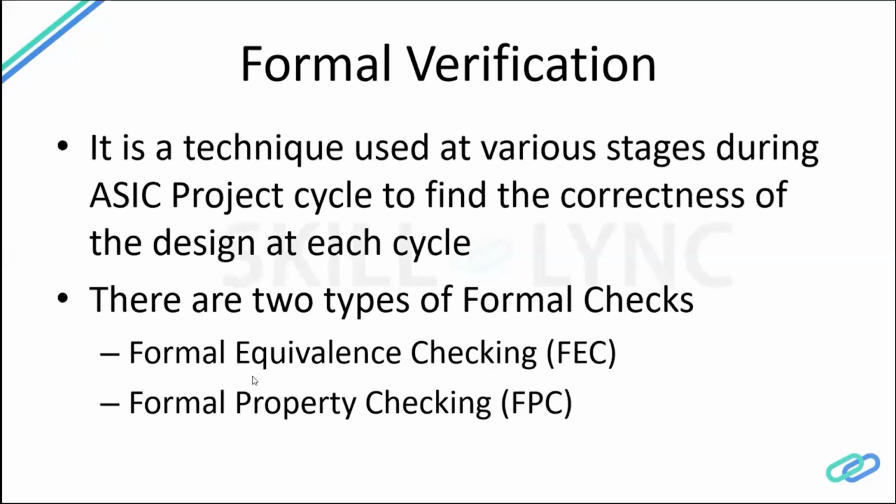From each point, it goes back in the RTL or in the netlist to calculate the logical value. If you give an input one, what should the output value be? Ideally, say you have a flip flop, with combo logic and a flop. If you give an input of one to this logic, assuming you have written code such that all the corresponding inputs are ones, it gives you a one at the output.